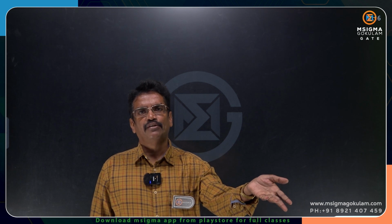Hello students, having discussed the infinitely long fin case, where I had given the formula for the temperature distribution and also for the heat transfer rate through the fin, now I will consider the more important case of the fin called the insulated tip fin case. Almost in every fin problem, by default, if he doesn't mention any case, we will consider that insulated tip fin case.